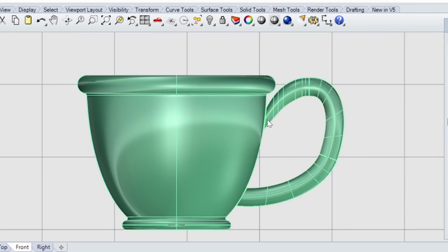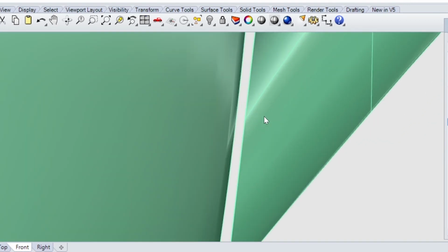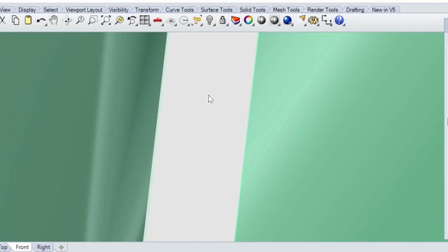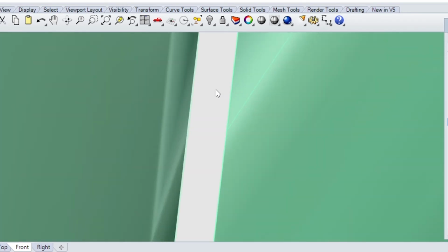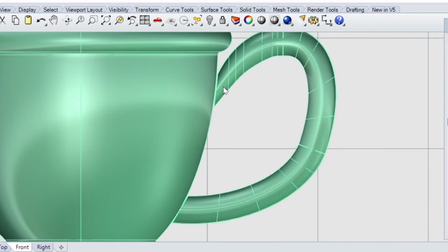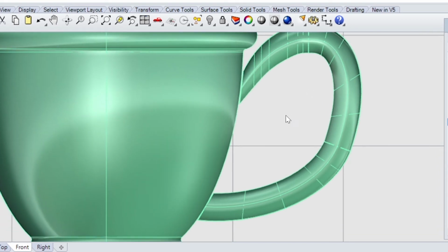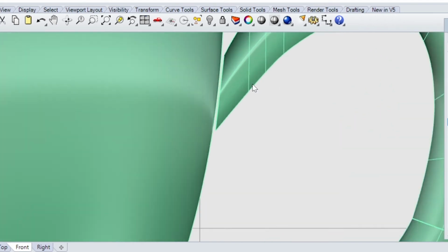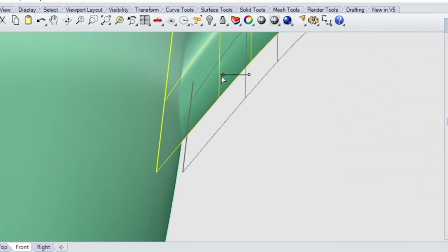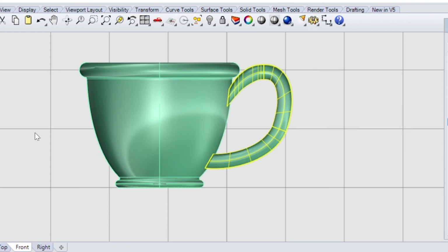And if we zoom in to that space between the two, you'll see that there is a 5-lane Washington, D.C. level highway in there. Unacceptable. A printer will look at this as basically a part that's floating out in space. It will try and print it, but more often than not, it will turn into a mistake, and it certainly won't be connected to the cup. So let's connect it to the cup. I'm just going to slide it over here to where they intersect, select both parts, and join them together.